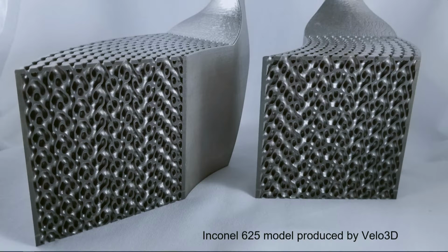That's just the beginning. Well, if you can even get past the geometric complexity, and by the way, what you're looking at is a heat exchanger off of an Airbus 321. The engine's a CFM 56. So 3 of these go around. It's an intercooler for cabin air. So to get the cabin warm, you take bleed air off the turbojet and you shove it through one of these. This is not the one that's on that engine.